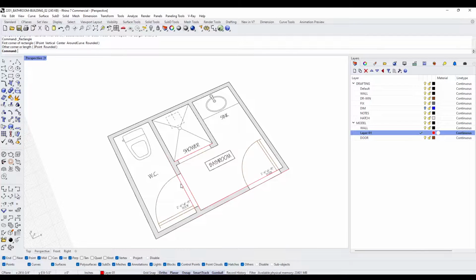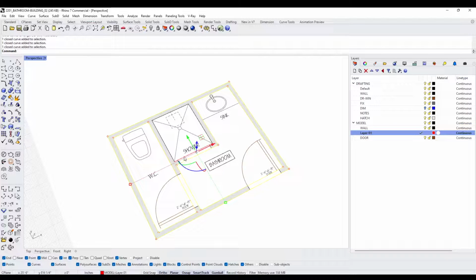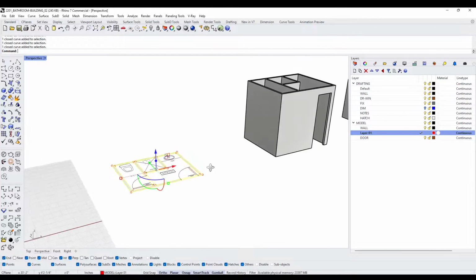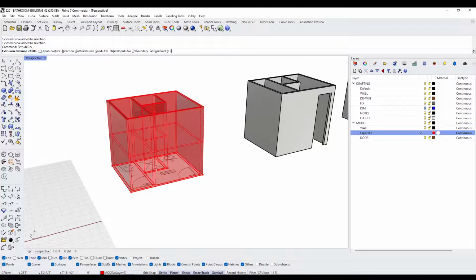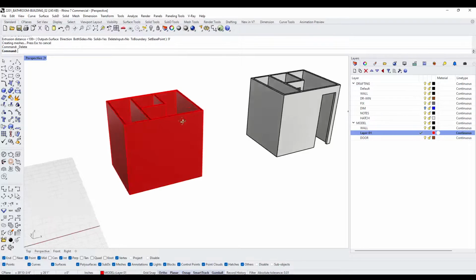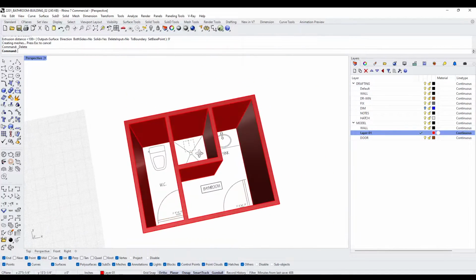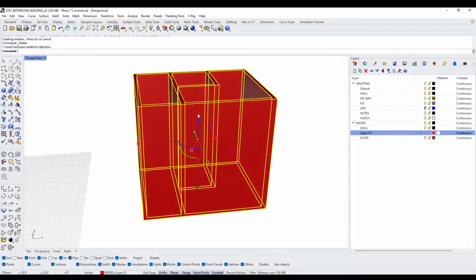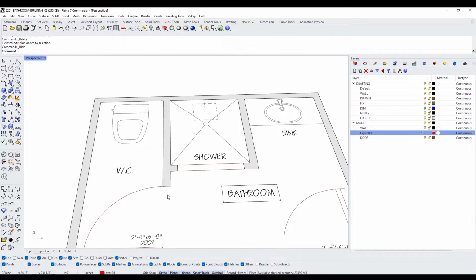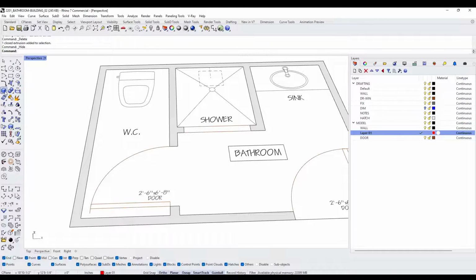All we need to do is remove the doors. So what I'll do is select them here. So I'll select that outer one, holding down shift, I'm selecting the other three. Now I can take this and do extrude curve at 9 feet. And that creates a perfect set of walls that we can now hide. And then here, 6 feet 8.